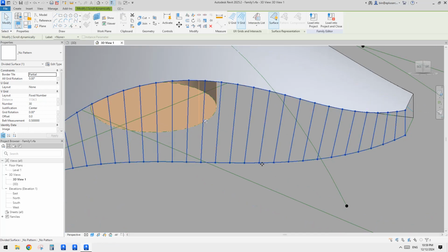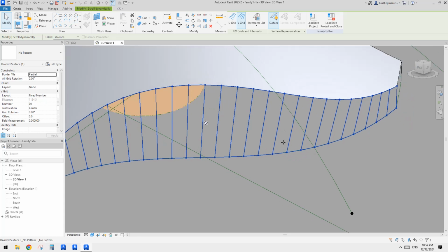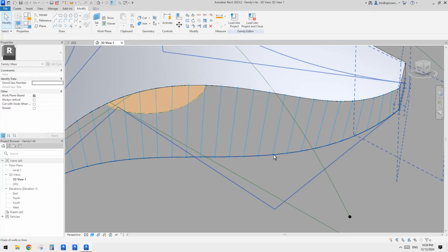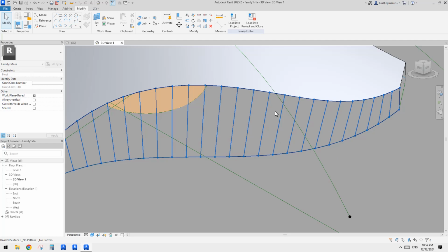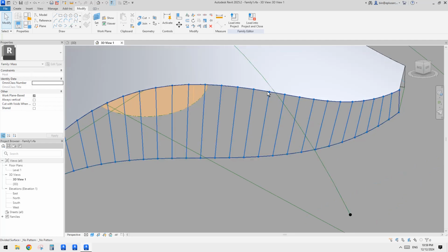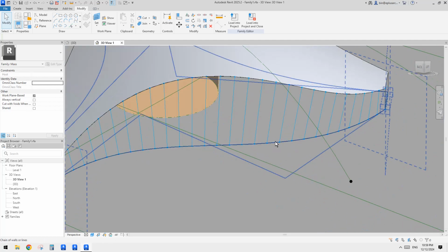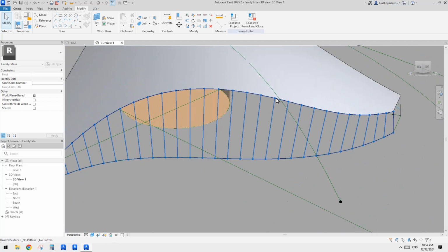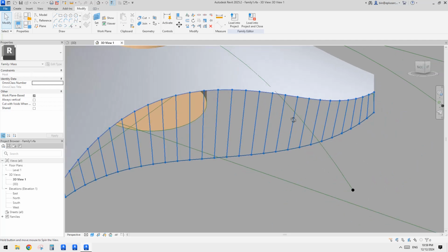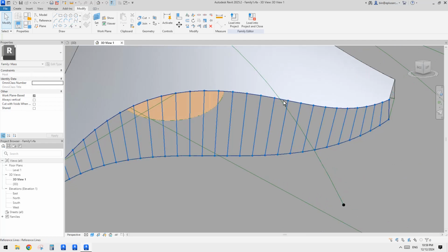There will be 4 adaptive points, so 1, 2, and then we need to pick this one and this one. We will make that family always vertical, so it doesn't matter where these 2 points are. We just need to place the 2 points at the floor level, and then use the other 2 to decide the height of this window, but not the location. Only the height.